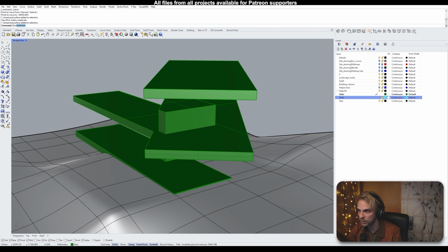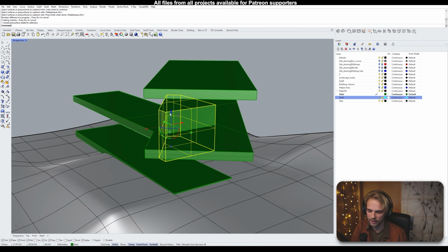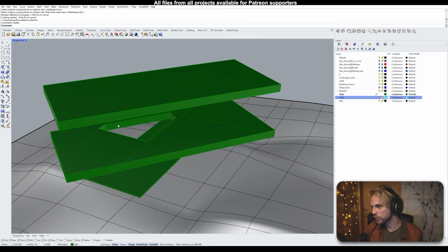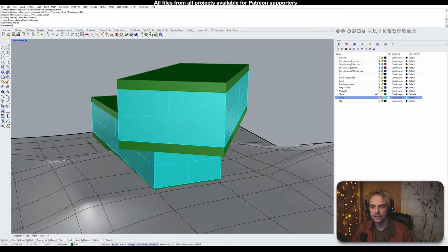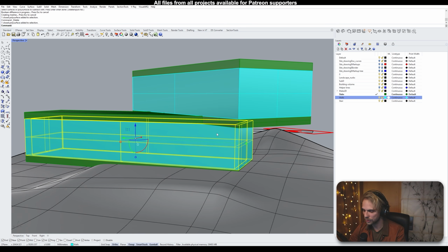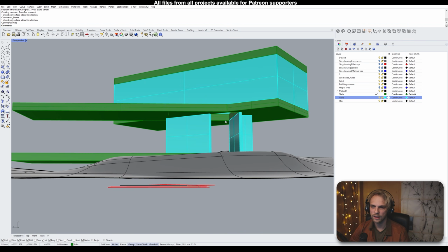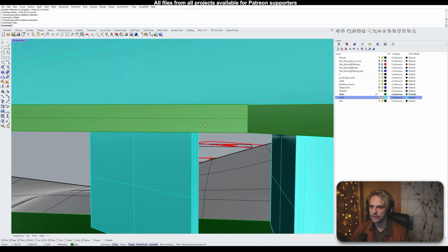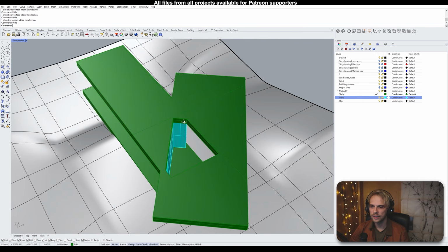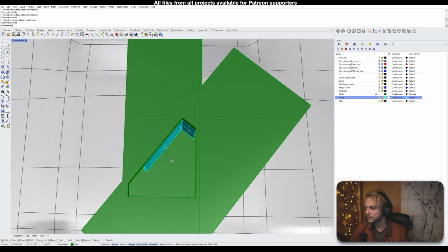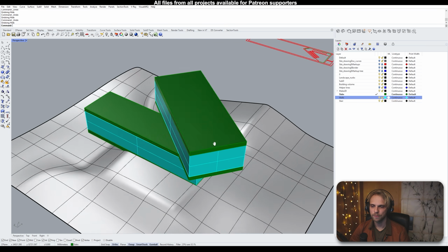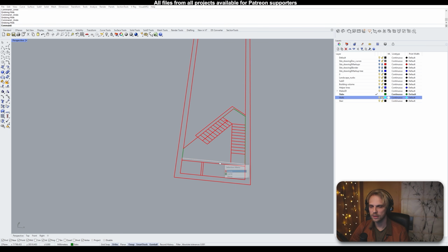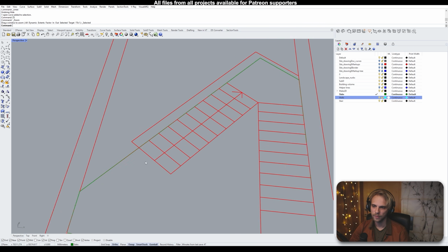And guess what I'll do? Boolean difference from here with here, or from here with this, then select it, delete it, and we have ourselves a hole. If I look at the walls, and let's select the outer wall here and hide the outer wall, you can see that there's a floor opening here that is waiting for us to actually give it a staircase. Speaking of which, let's model out a staircase. It's going to be pretty straightforward. I'm just going to...